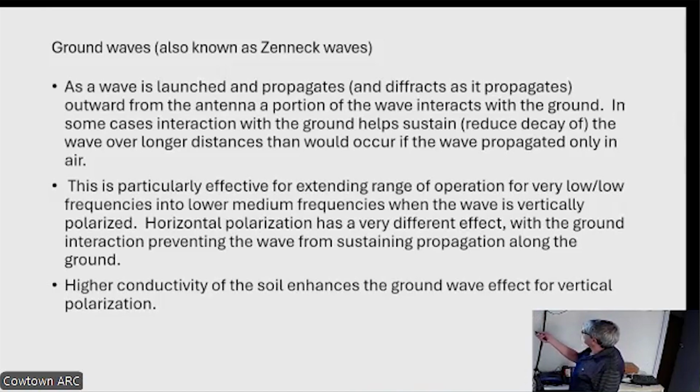The higher conductivity of the soil enhances the ground effect for vertical polarization, which is kind of interesting. But at higher frequencies, this isn't effective. Charge movement within the soil is less efficient at sustaining the wave as you go to higher and higher frequencies. There's more loss involved.